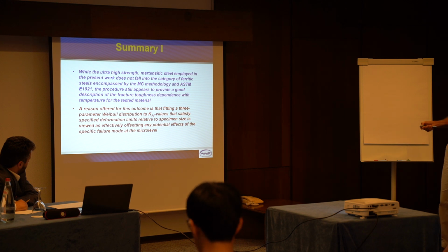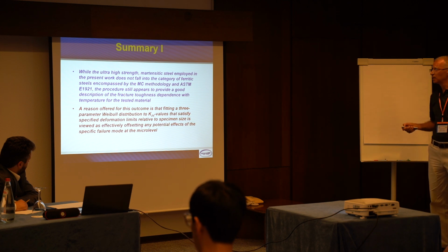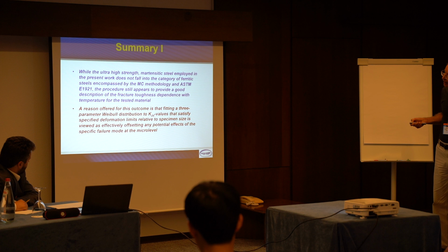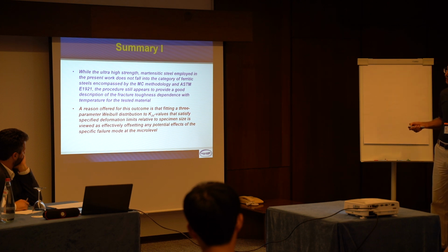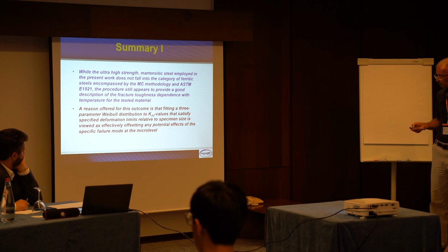One of the reasons for this, let's discuss this later, is that it's actually not very important if you satisfy cleavage fracture, which is what the standard tells you. You need to satisfy cleavage fracture, but you saw a lot of dimple structure. So it looks like it's much more important to satisfy the statistical distribution, the Weibull fitting, than the actual micromechanics of the microstructural failure.